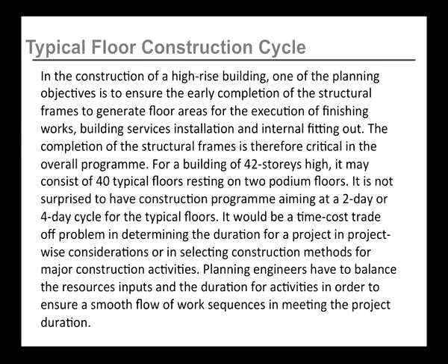The completion of the structural frames is therefore critical in the overall program. A building of 42 stories, as an example, may consist of 40 typical floors resting on two podium floors. It is not surprising to have a construction program aiming at a 2-day or 4-day cycle for typical floors. It would be a time-cost trade-off in determining the duration for a project, or in selecting construction methods for major construction activities.